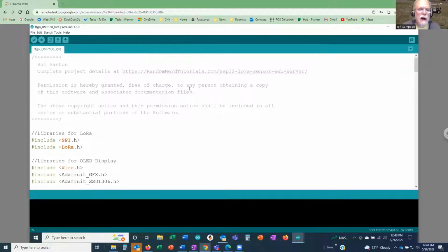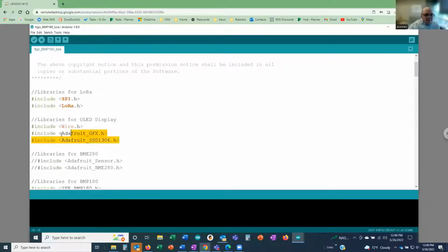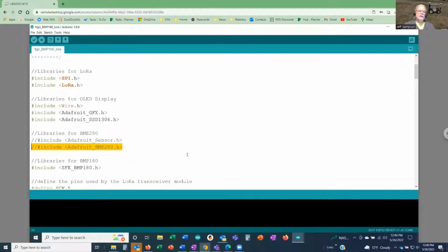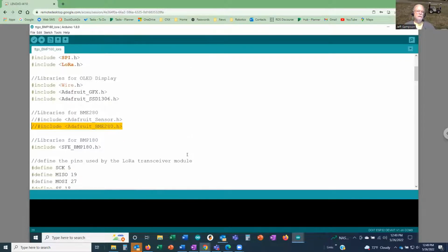Okay, so I assume on that one he's going with the Adafruit stuff. That's what he usually uses. So you've got the problem where it's trying to use the Adafruit I2C libraries, but you've included a library, in this case from SparkFun. You're probably going to have a problem there. It could be that that name is not included, that's not the correct name for the header file.